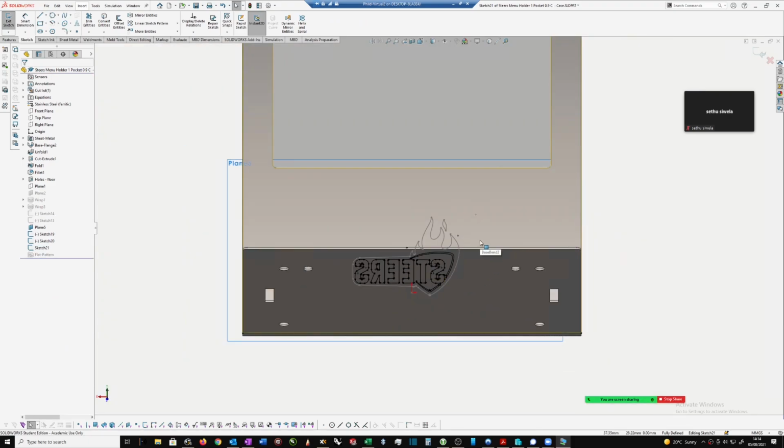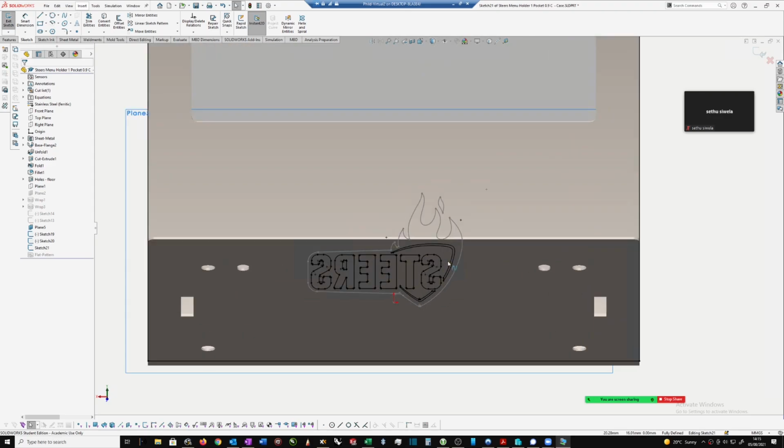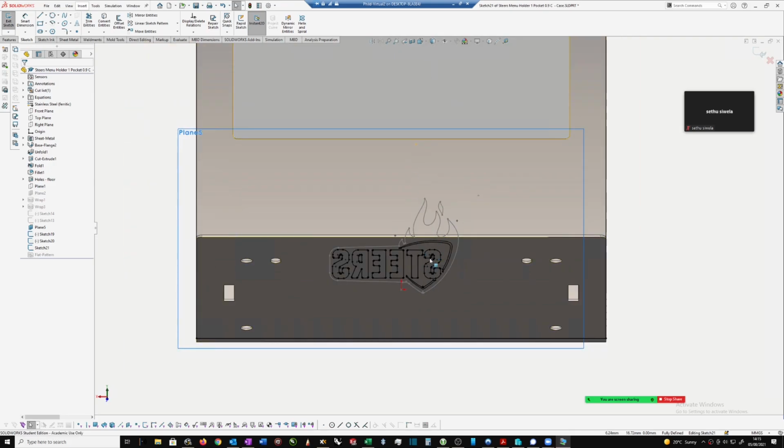By the way, a quick trick, if you can't see, like if there I couldn't see what was going on, you need to see what your sketches are. Just go to this button at the top here and select shaded without, and that'll instantly allow you to see where your sketches are. So put that back on. So this one's in place.